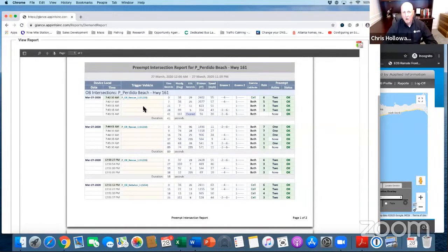All of the equipment that's installed in the field has what we call a green sense harness inside, installed in the traffic cabinet, and that tells us exactly what the greens are doing during the cycle. So in this particular situation, this rescue 1 was approaching this intersection, and as Jeff took you through the way you see how a preempt occurs, we can see that initially, whenever the call came in, the light was already green in the direction that he was wanting to travel.